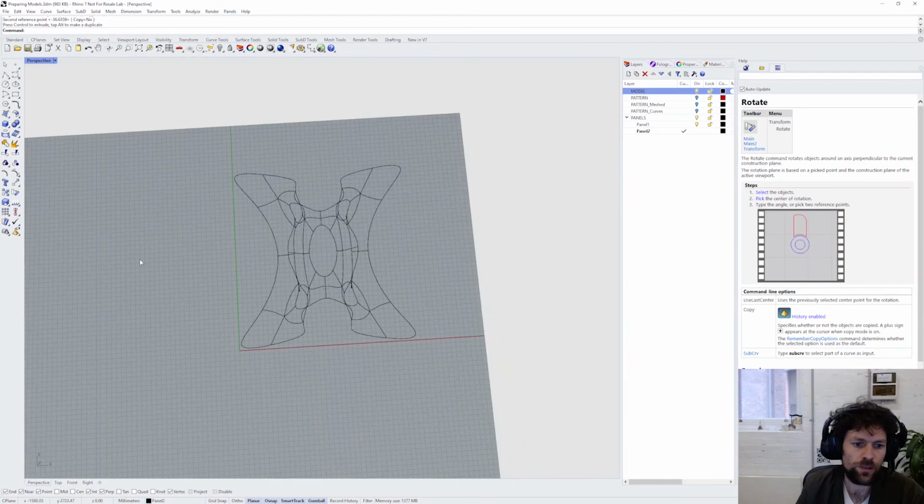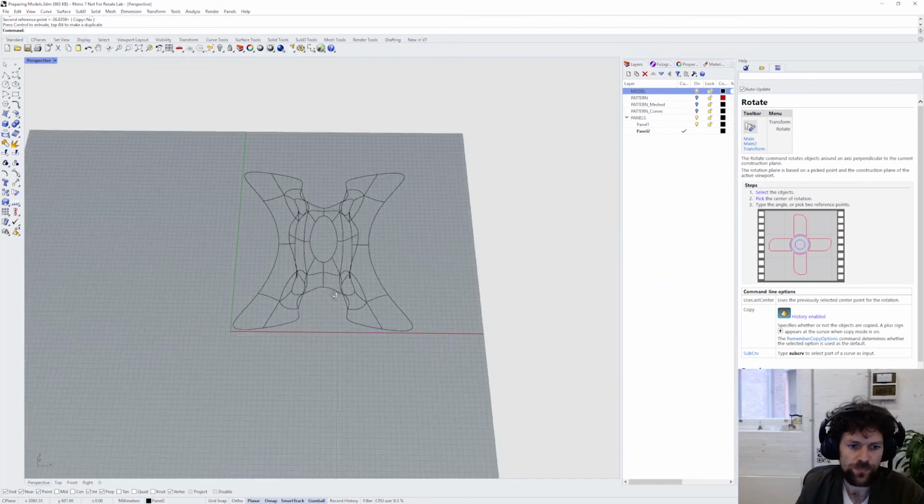So keep models oriented at the origin and aligned to your Rhino axes where possible, especially with Fologram. This will make it easier to set out using the Fologram QR code. With TwinBuild, it's not going to be so challenging. You'll need to locate your model specifically relative to the markers that you've set up in your workspace.